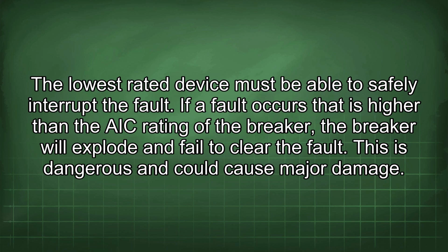If a fault occurs that is higher than the AIC rating of the breaker, it will explode and fail to clear the fault. This is dangerous and could cause major damage.